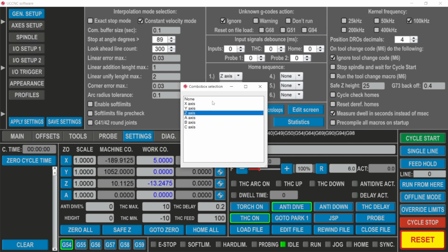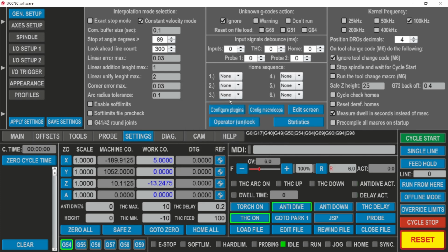Lastly are the settings under kernel frequency. Kernel frequency is essentially how many pulses the computer or the board must utilize over a given amount of time. With the AXBB, we can select any frequency. However, with a CNC with more functions and a higher demand, a higher frequency would be desirable. Also, it is important to note some components or boards require a certain kernel frequency to function. It is important to remember to save and apply settings as we move along.